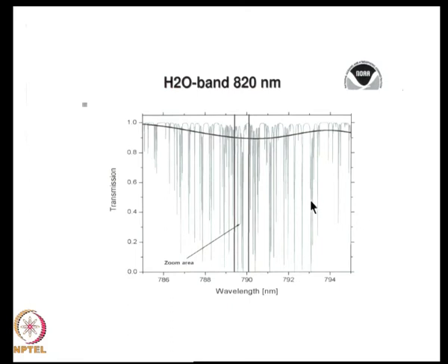So, you have to tackle this high absorption at the central line along with the adjacent wavelengths having no absorption. So, this is the challenge of calculation in radiation heat transfer, that the absorption of the gas varies strongly with wavelength, and a small change in wavelength or wave number or frequency causes a large change in the radiative flux.